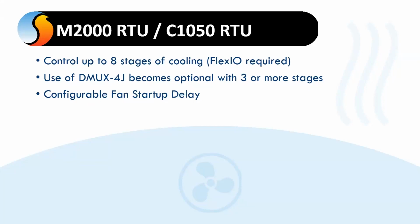So your configurable fan startup delay is going to stage those fans in sequence, and we don't start counting for the compressor timer until that fan is proven. Okay, so this is your delay to avoid those massive surcharges for demand caused by multiple simultaneous inrush current of multiple motors turning on at the same time.